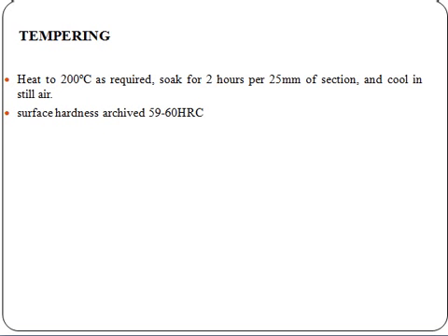This one is the carburized, annealed and hardened microstructure. Material EN353 same. Micro: untempered martensite inside with 15 to 20% RA. RA means retained austenite. Hardness 59 to 60. The next one is the carburized, annealed, hardened and tempered microstructure. Retained austenite and martensite are shown here.